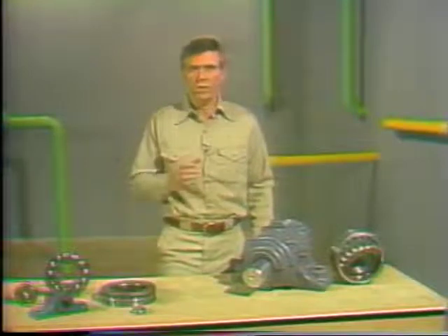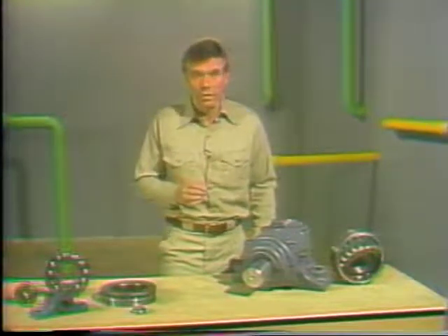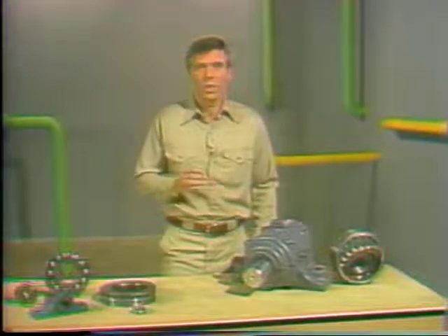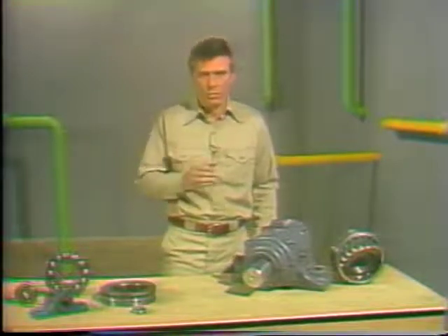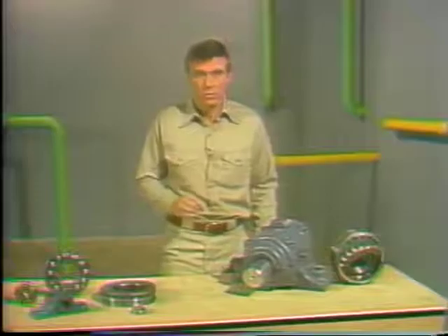Friction is the resistance to motion that exists between two bodies in contact with each other. In order to move one or both of these bodies, friction must be reduced. The majority of bearings fit into one of two categories: sliding surface bearings and rolling contact bearings. With sliding surface bearings, two surfaces with a lubricant between them slide over each other, like so. With rolling contact bearings, one surface rolls over another surface with lubricant in between.